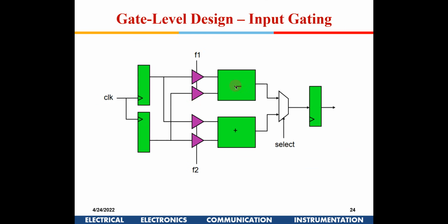This is the second last slide, in which many circuits, as we discussed in the ALU design a few days back, have some data coming here. This is doing a subtraction operation. Suppose this is doing an addition operation, and then you have a mux which will say, okay, data A plus B from this module will be routed towards the output, and A minus B from this module will be routed out here. So this is the general thing.